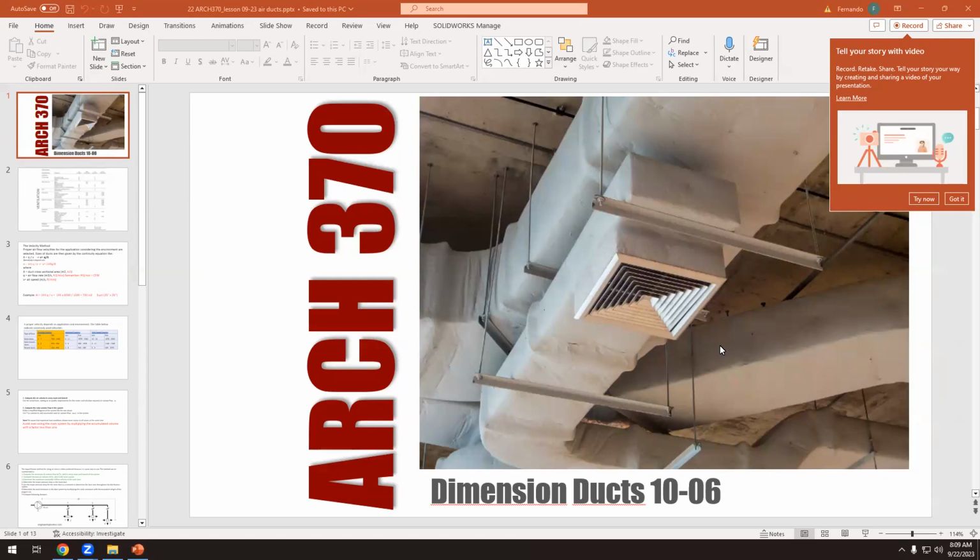And then the problem with this is that we need to increase the height between the false ceiling and the structural element and the slab, and that means that we need a higher building, and that means that we have to build more volume, and building more volume means that we have to spend more money. Okay, so if we try to prevent all these conflicts, we will save space, and saving space is saving money,